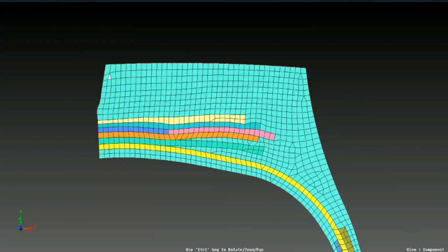Again, we have other options like align nodes, replace node, swap, smooth, move tria. This move tria is also an advanced tool where the user just has to select the tria so that it will highlight a path where this tria can move from one location to a different location. So let's say I click on this tria and I select any other highlighted element, and it will go ahead and move like this. So by using this advanced tool, the user can very nicely go ahead and create a smooth and high quality mesh.